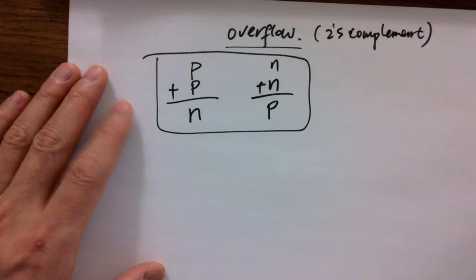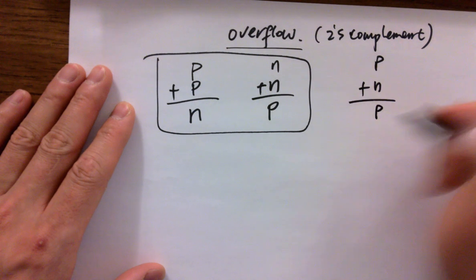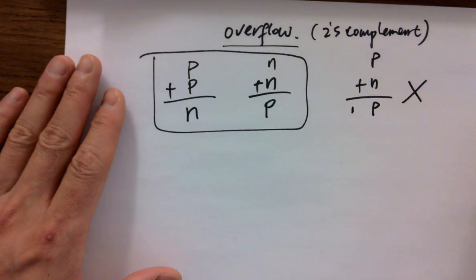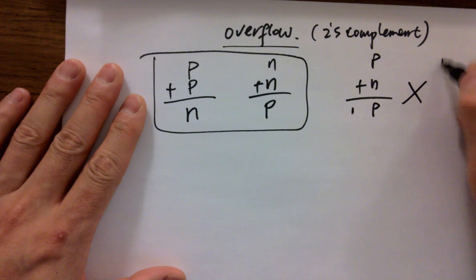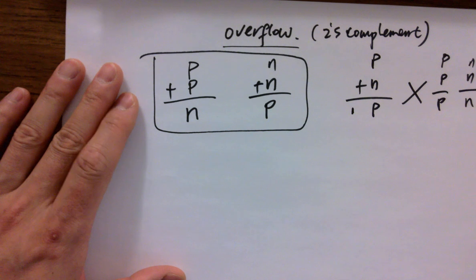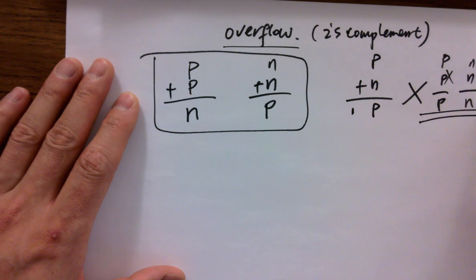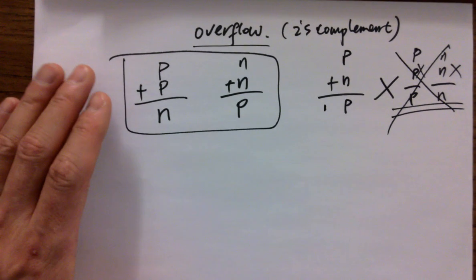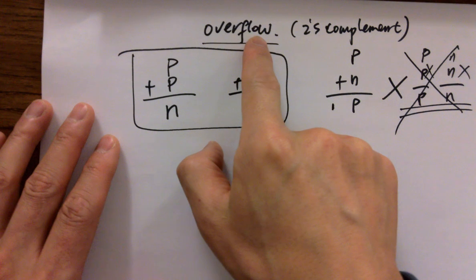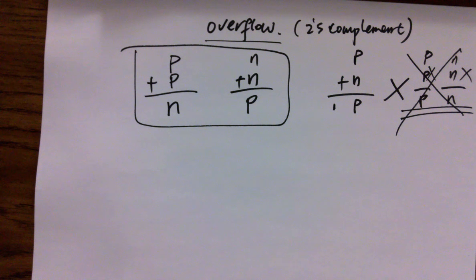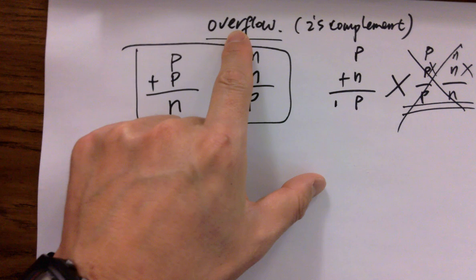Only 2 conditions. If you have a p plus n, you're getting a p, but there's carry out, it's not overflow. P plus P, you're getting a P, no overflow. N plus N, you're getting an N, it's not overflow, even though there's carry out. No overflow for these cases. So the definition for this is very useful. After the lab next Tuesday, you will be able to find out why it's useful, because we need that logic to generate that overflow bit for the calculations.